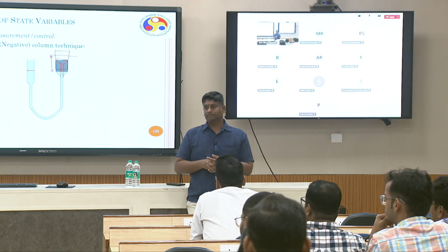Sir, another question that I have, from the pavement point of view, both the subgrade and granular layer. Even the South African guidelines and the US-based MEPDG mostly have a plastic deformation model which takes into account degree of saturation as a function. If it has to be done for the Indian context, how should that be a function of degree of saturation? Degree of saturation is a function of what?